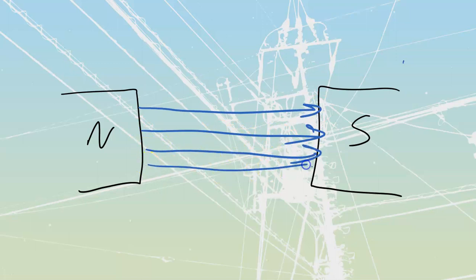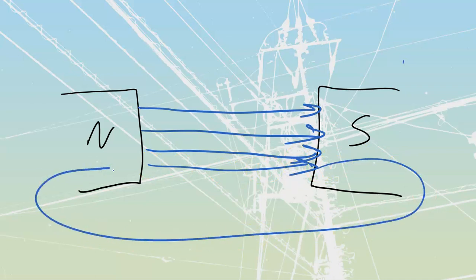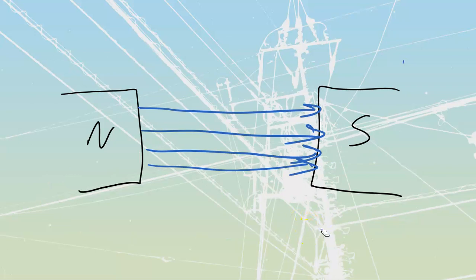One, they like to form complete loops, which means they're going to enter in here, travel back through the outside casing of the machine, the stator, back through to the other side. They also possess the fact that they cannot cross each other. Magnetic lines are not able to cross. And last of all, magnetic lines possess a force of elasticity, which means that they are always going to stretch as tight as they can, but they are able to be stretched in other circumstances as well. We're going to see that happen over here when we insert a current carrying conductor.